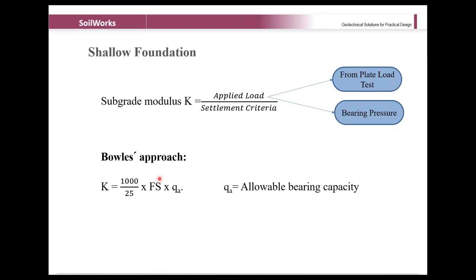So basically, for shallow foundations, we can either go for the plate load test, or we can determine the bearing pressure, or we can use the Bowles approach in order to determine the springs. That's as simple as that, and this can be easily dealt with by the structural engineer itself. And when we go for the deep foundation, it is more complex, and how this software can help you make a bridge from that complexity to an easy approach, we'll be discussing in this session.